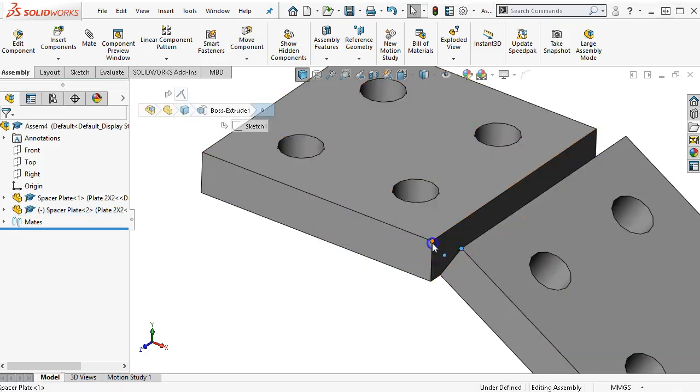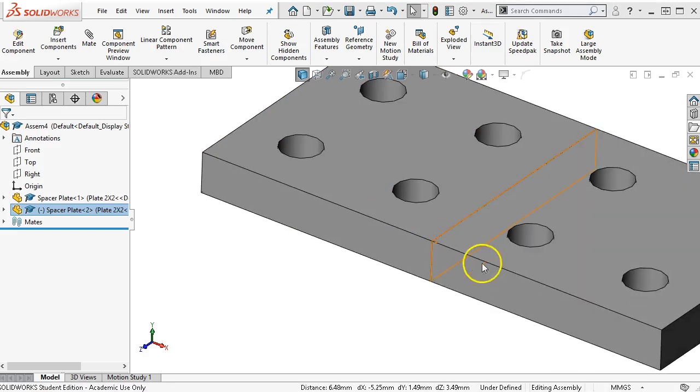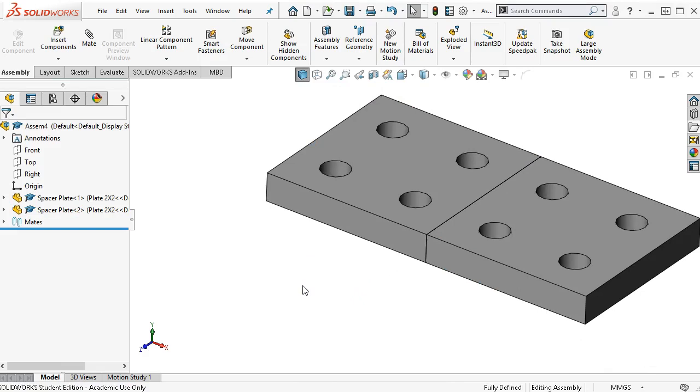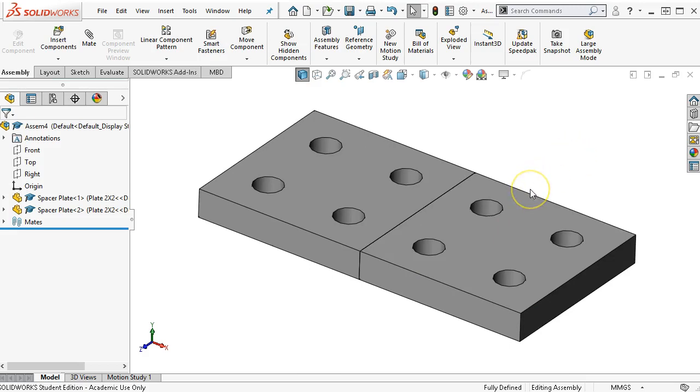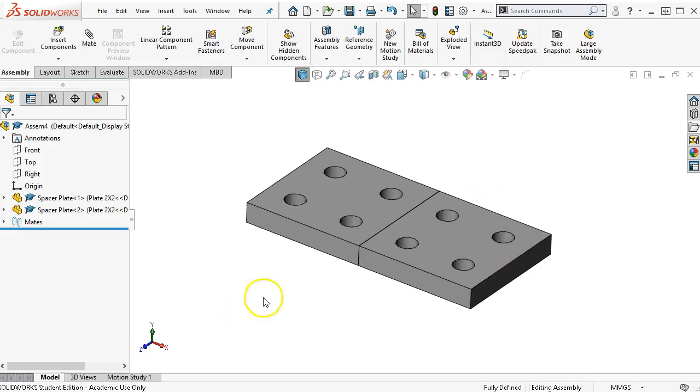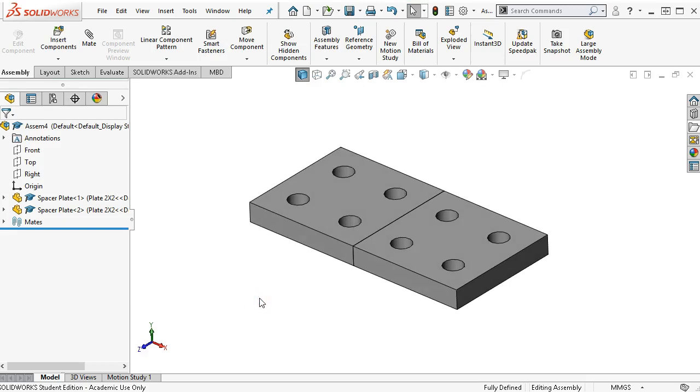If I go with an edge and a point, then I get the same result. The only problem is that if there's an issue later on, it will usually be because the assembly with the pointer along that edge had some kind of issue. It lost its mind. And maybe this is a problem from 10 or 15, 20 years ago that I'm still holding on to, but I think the most stable is to go face to face and pick a strategy and stay with it. If you don't ever run into any problems going for edges and points, then stay with it.